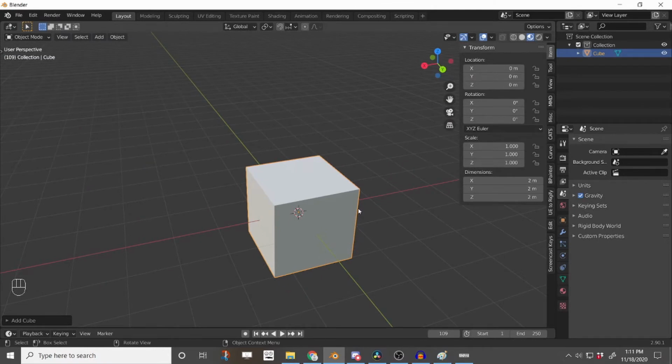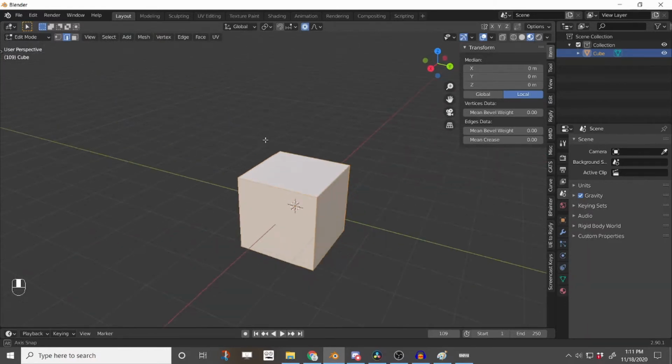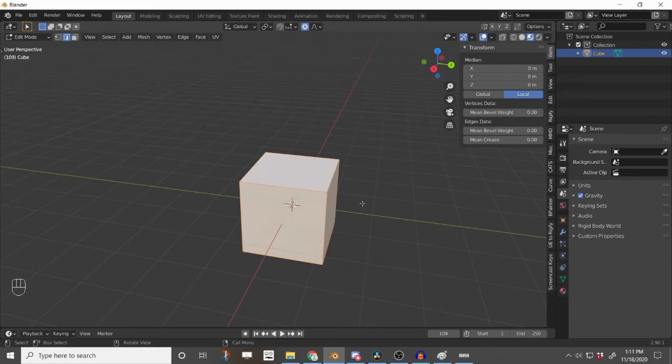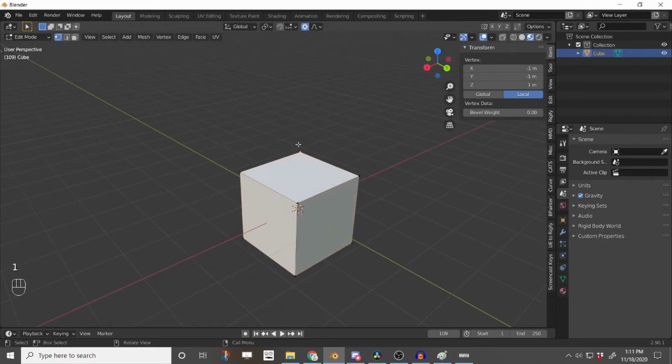You can go into edit mode a few ways. You'll learn that Blender has many ways to do one thing. It's whatever your preference, it's whatever your workflow becomes. You could go up here, the top left of the viewport, and go down to edit mode. And this will take us into the mesh of the object. And so if you press 1, then you get vertices.